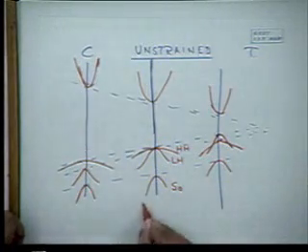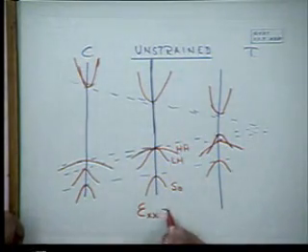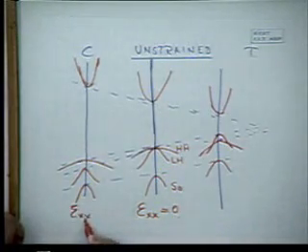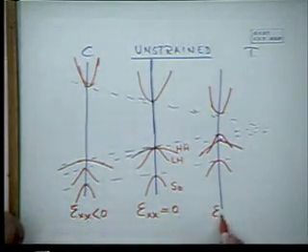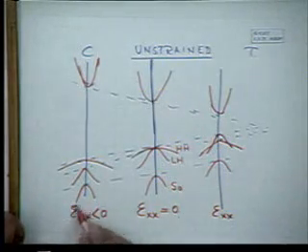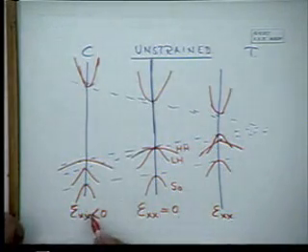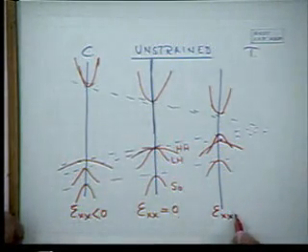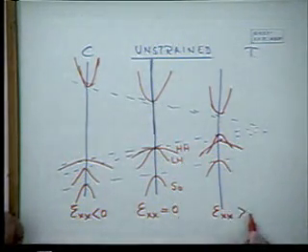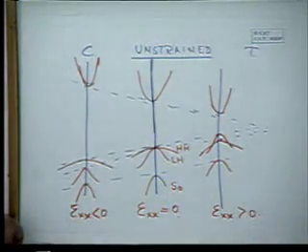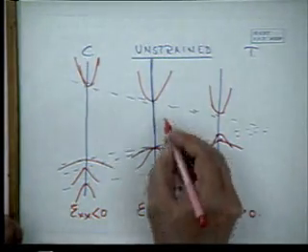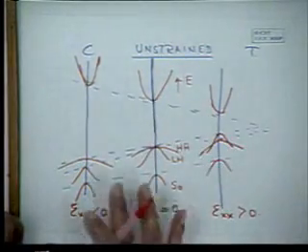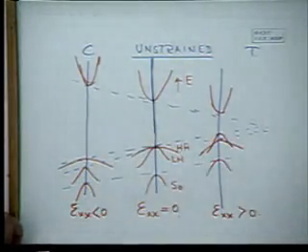So here, the strain epsilon XX. This is epsilon XX less than 0 for compression, and epsilon XX greater than 0 for tension. Okay, this epsilon is delta A by A. So for compressive strain delta A is negative, so delta A by A is negative, and here for tensile, epsilon XX is greater than 0. Okay. So this, in a nutshell, is the effect of strain on the band structure.